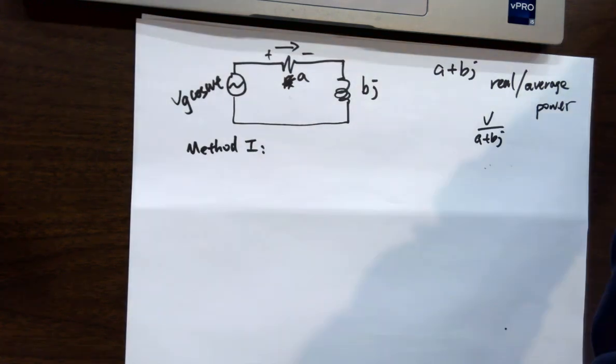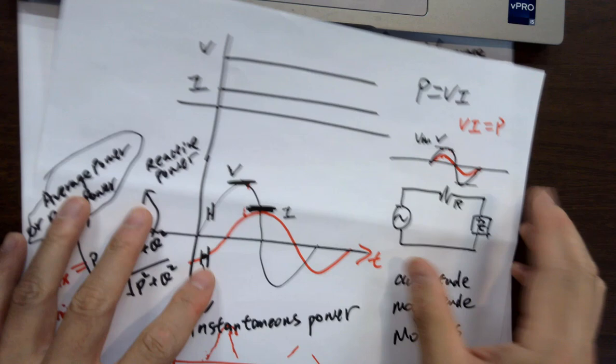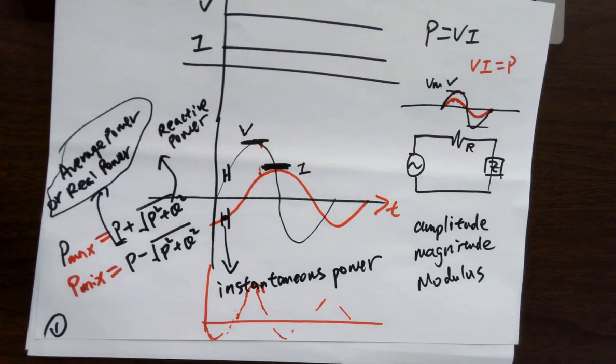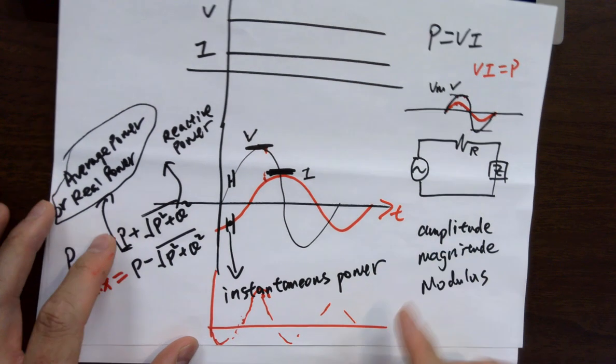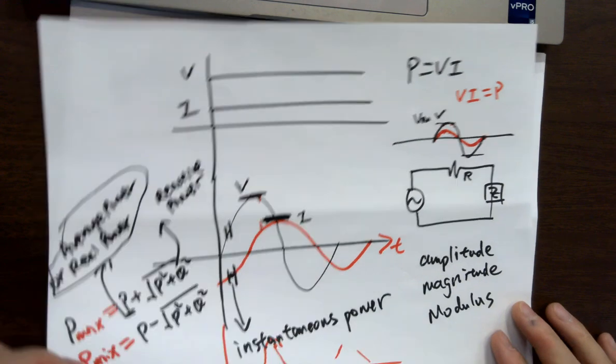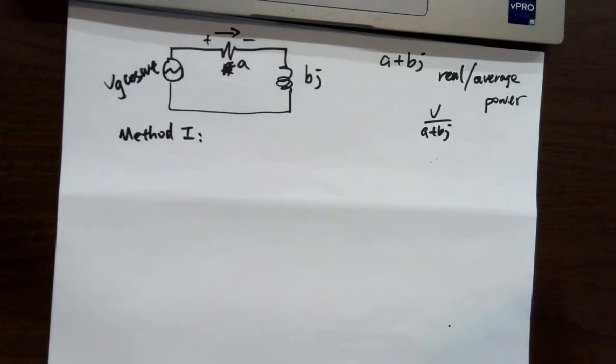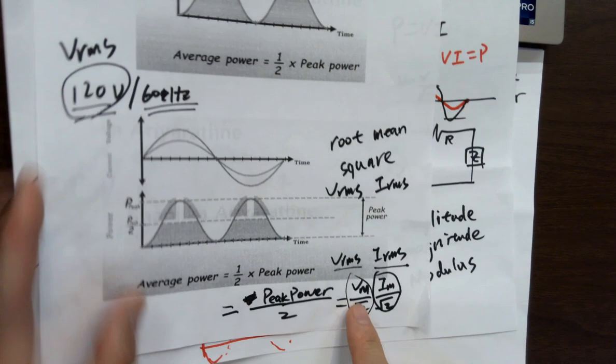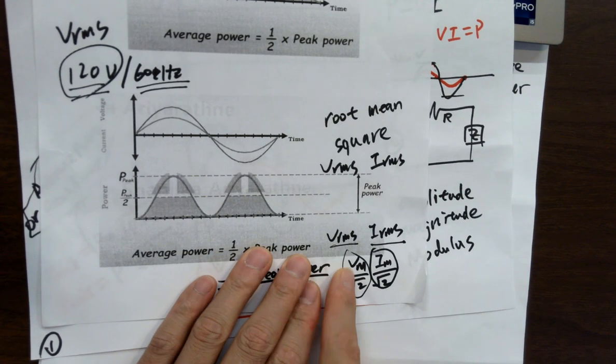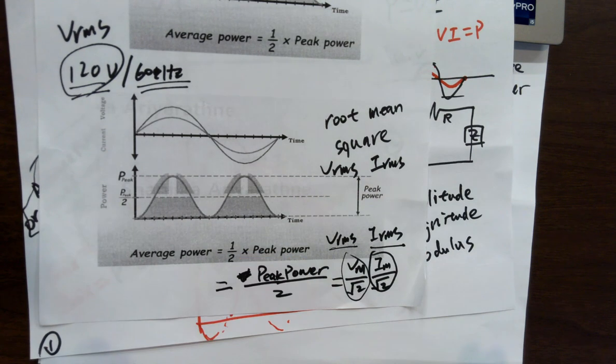So let's come back to this point. It will all come together, trust me. It's not difficult. Electrical engineers eventually found a way to characterize the power system, power consumption. That makes sense, right? How do we do that? Using RMS values. We can use RMS values to calculate the power of the AC power system. How do we get RMS values? Super simple. The peak value divided by square root of 2. That's it. Okay? Good here?